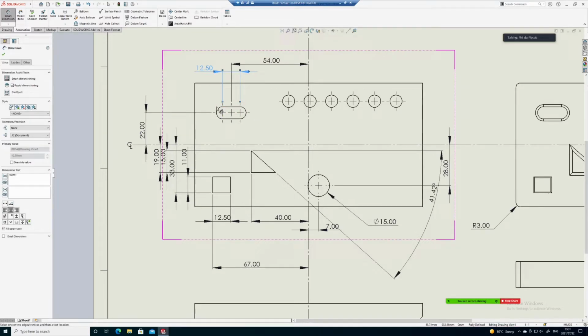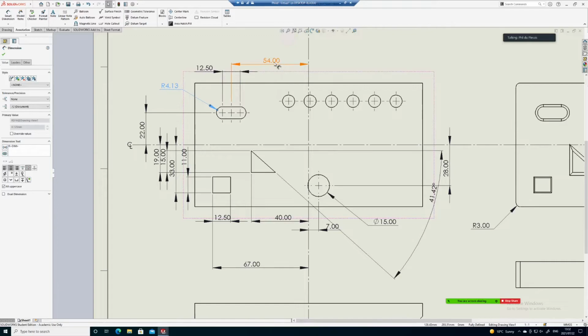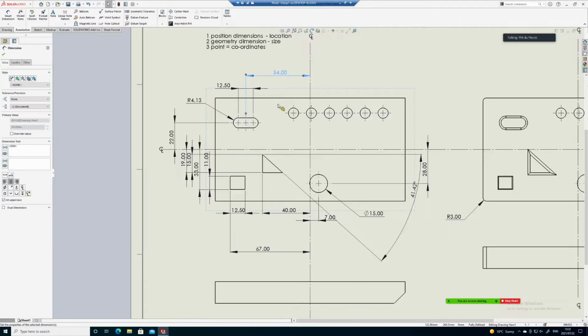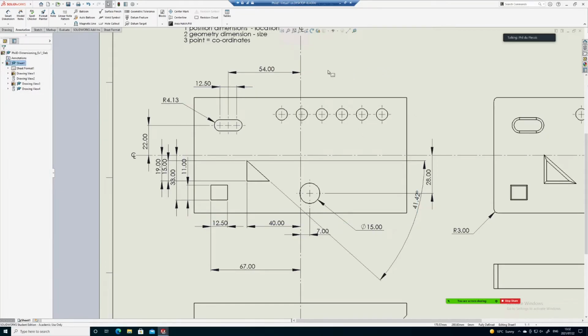And then here you've got to decide what's important for you: either put in the width of the slot, or you can put in the radius, but not both, just one of the two. You don't need both, and if you put in both, you're doing the thing that I don't like. Well, no one likes redundancy in a drawing. Well, no one who uses drawings likes them, let me put it that way, okay? So you just have to put up with my idiosyncrasies here.